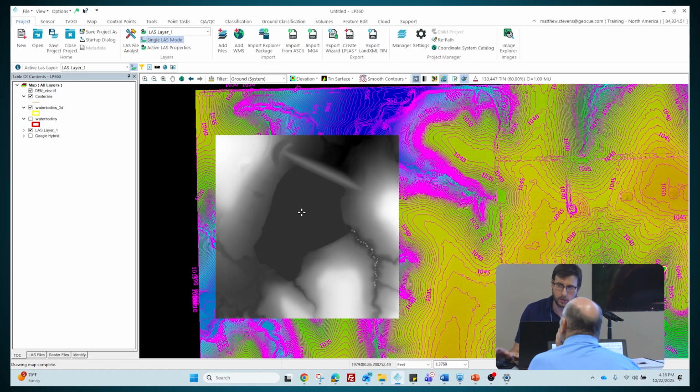It's a bunch of randomized points with LAS data typically, as you guys have noticed when you're dealing with this data. My DEM has this nice gridded data set, so we can make a LAS file based on the DEM and also check the DEM and make sure that what we created is correct, and also make a gridded data set at the same time.